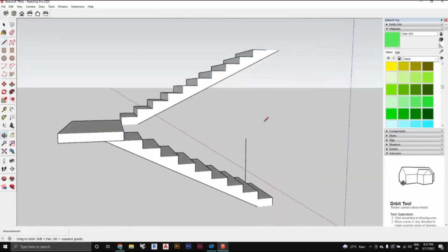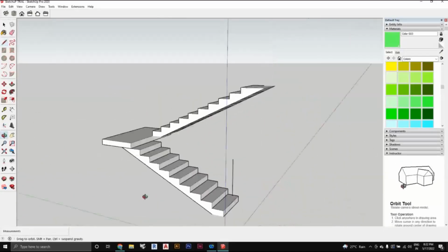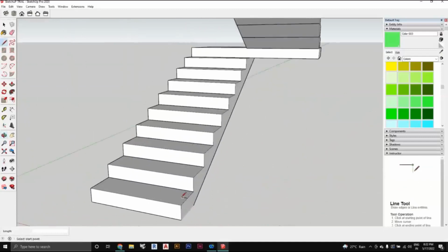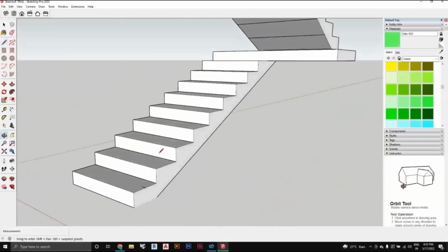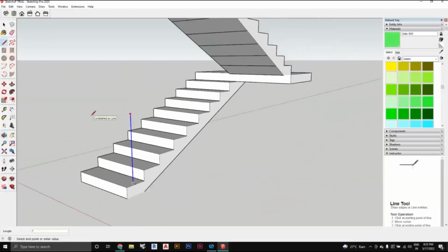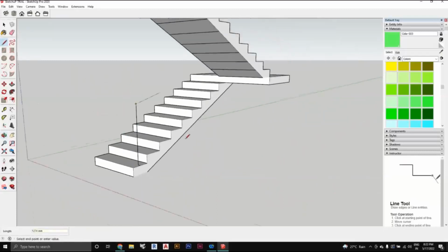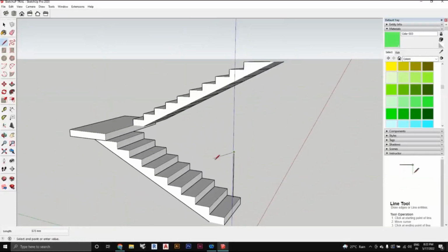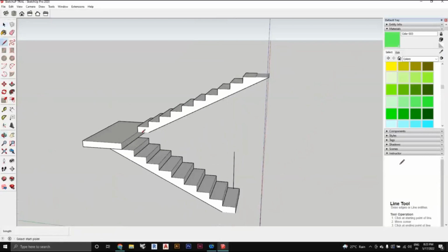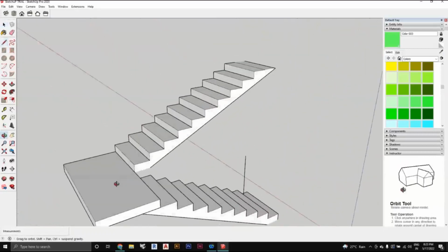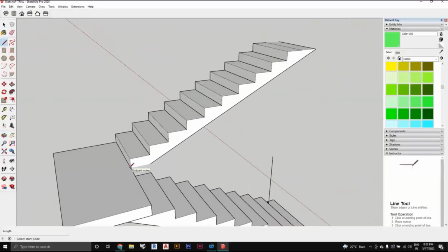so I get a straight line on top. I used the arrow key only: I'm selecting the top arrow key, and when I use it, it locks onto the top axis, and then I'm typing 1000 and pressing enter. So you get a straight line. Then I'm pressing the space bar and going back. Then I'm again using the line tool and creating another balustrade on the top.